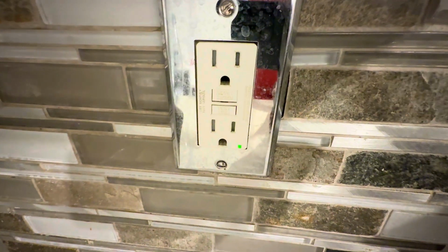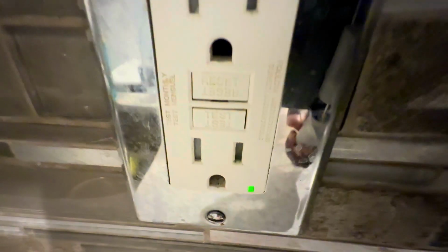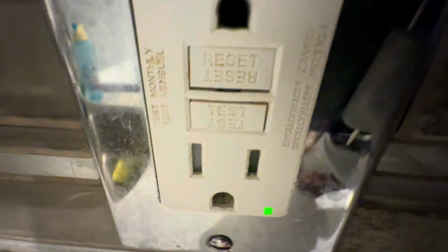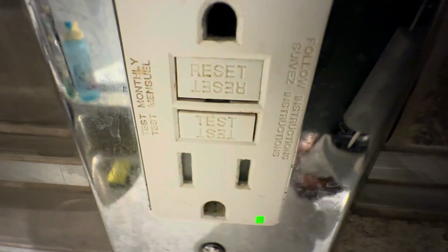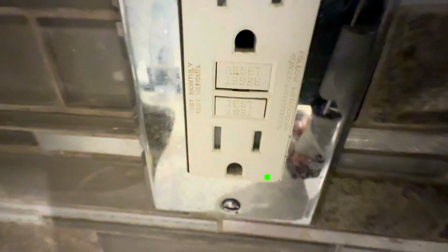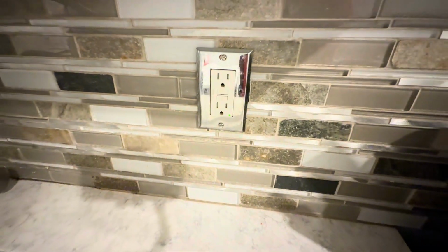So how can you test a GFCI? Normally a GFCI has 2 buttons, one test button and one reset button. When you press the test button, the GFCI will trip, and if you plug an equipment into that socket outlet, it should not turn on. You should not be able to turn it on. But if you press the reset button and you turn the device on, the device should be on. That's how you can test. That's one method to test the GFCI at home.